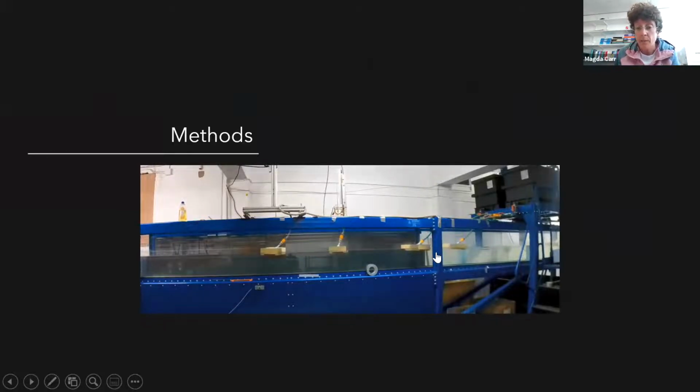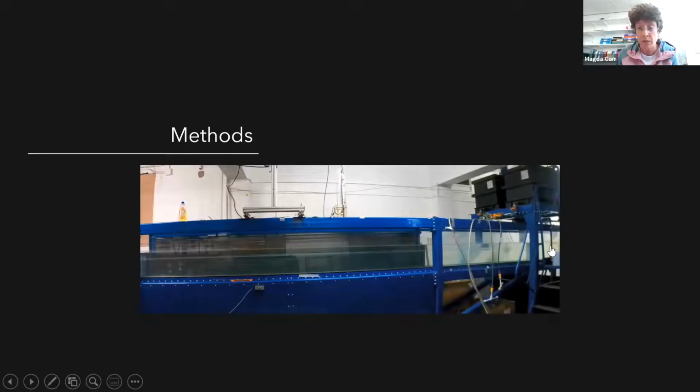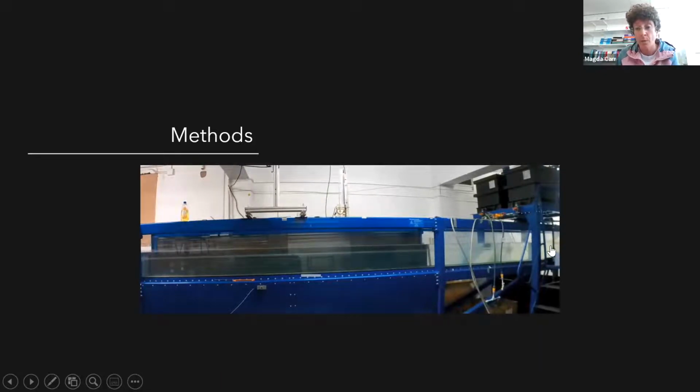Once that's complete in the main section of the tank, we have a gate, which we put in the upstream end, which you're not going to see in this particular movie. We fill behind the gate with that fresh fluid, and that gives us the density gradient to drive the wave. So everything you're going to see today is driven purely by buoyancy. There's no mechanical forcing.